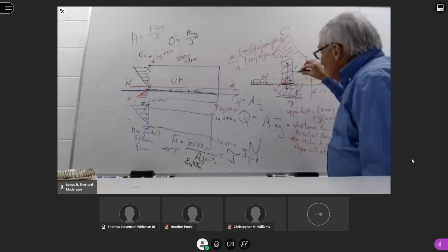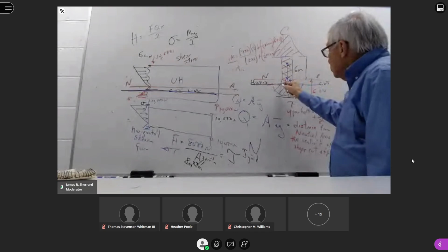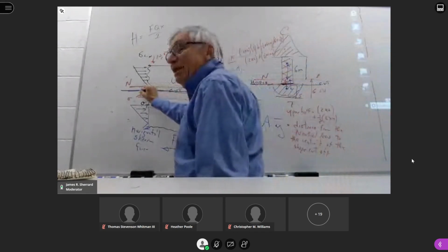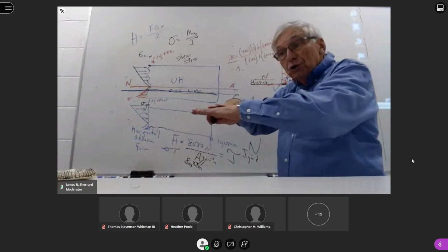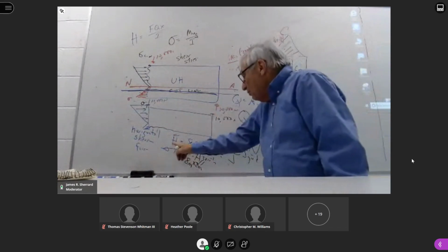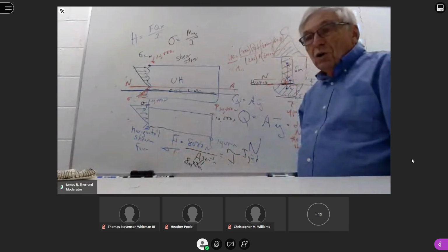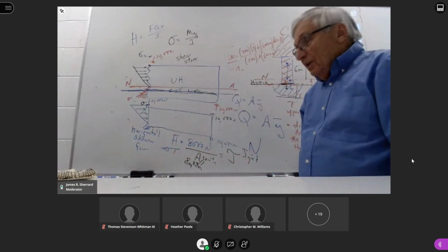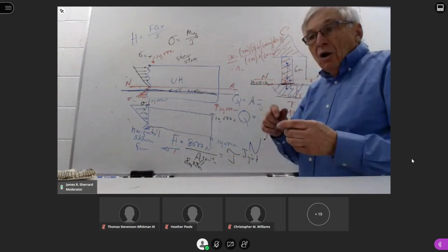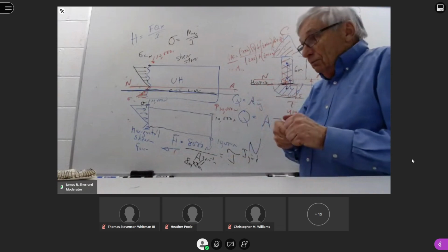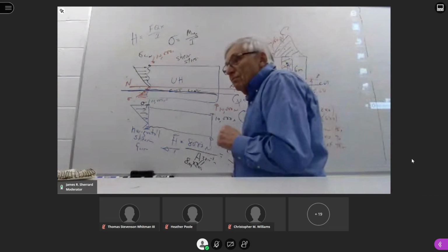So what you have to do is you're looking at a plane that is 2 centimeters by 8 meters. So this force is acting parallel to that, and that's how you convert the force to a horizontal shearing stress. And then you could compare that to the yield value to see if that was going to fail along that line. Okay?